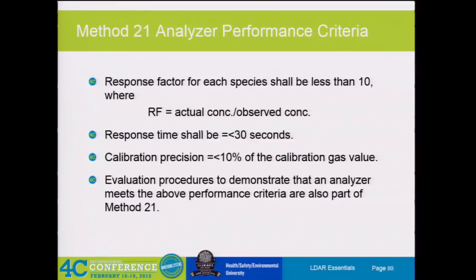We'd find it at 800 and he would get 30. And then we'd find it again at 800 and he would get 30. So we kept going through and tried to do a whole bunch of troubleshooting, and we were there more not to audit but to help find a solution and help coach and help teach how to properly do Method 21. And from there, what we found out is when he would go in to calibrate, we were getting perfect numbers. When we were pulling drift checks, he'd get 500. And we could not figure out what was going on.